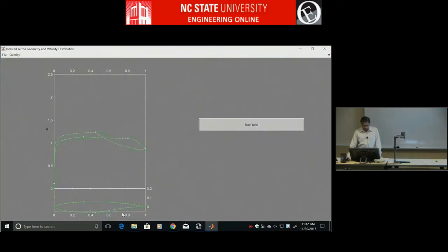Okay, so it's happened. You can see this is the lower surface phi, right? Lower surface segment endpoint 3. Earlier it was at 45%, now it's at 55%. It's exactly at 55%. I mean, maybe to some 5 decimal places or something, it's probably correct. That's why Newton iteration is so good. Now I can go and change all kinds of alpha stars and do all that other stuff. This will always be nailed at 55%.